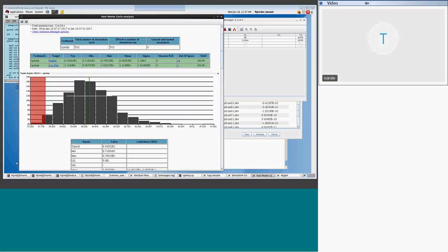and use the Variability Explorer that was just mentioned 2 minutes ago. We don't really advise using Monte Carlo for 3 sigma or more because 100 simulations is really a huge number. And we propose the Variability Explorer. The Variability Explorer is like a fast Monte Carlo, with the main difference that it will focus on the tails of your distribution and detect the fails, if any.